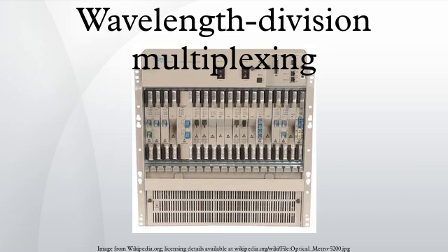1R, retransmission. Basically, early transponders were garbage in, garbage out, in that their output was nearly an analog copy of the received optical signal, with little signal cleanup occurring. This limited the reach of early DWDM systems because the signal had to be handed off to a client layer receiver before the signal deteriorated too far. Signal monitoring was basically confined to optical domain parameters such as received power.